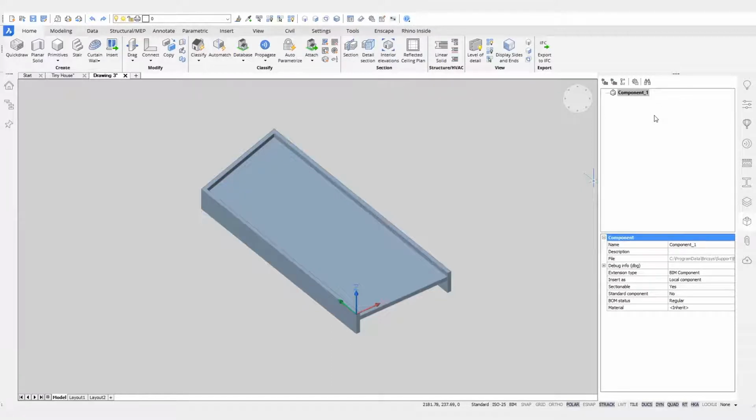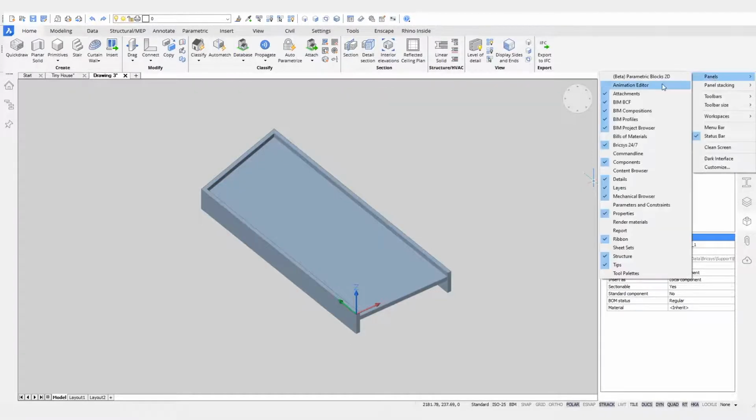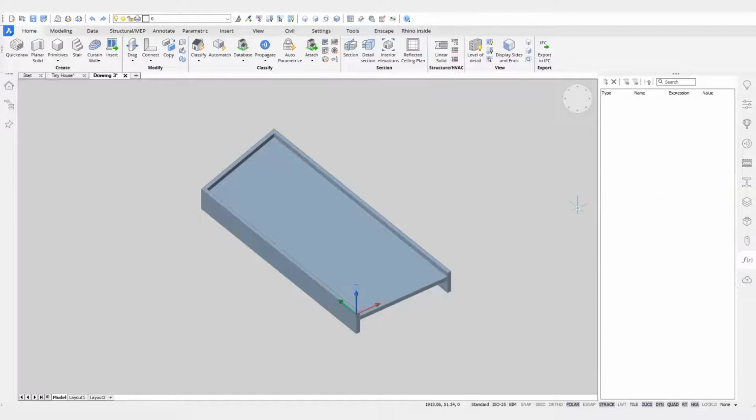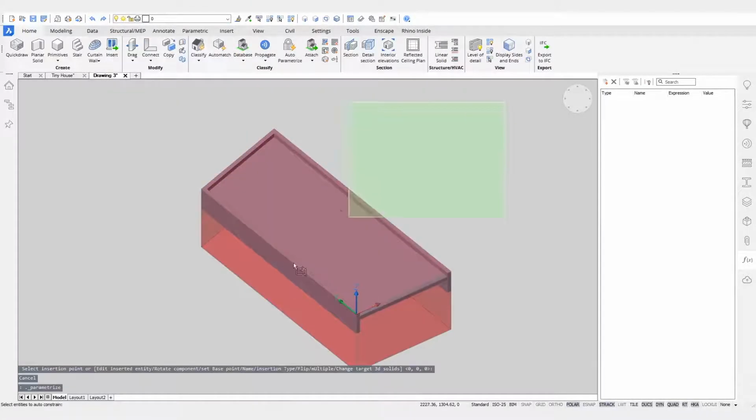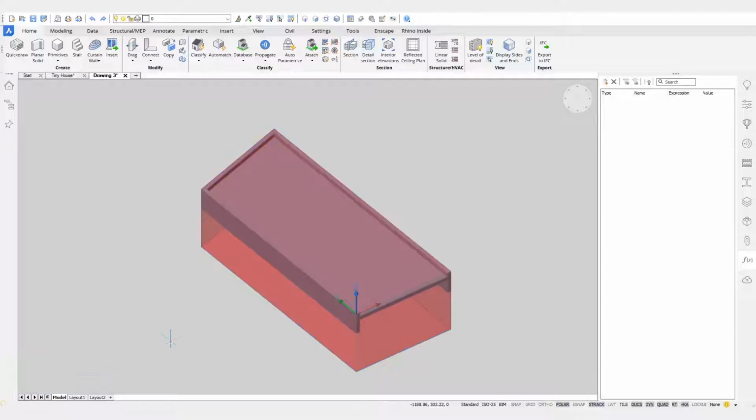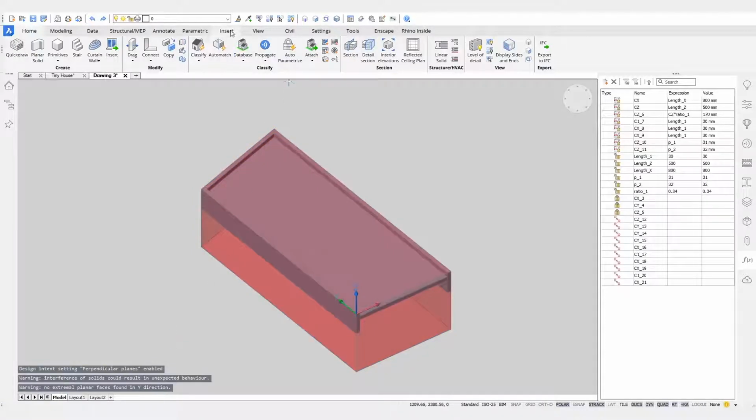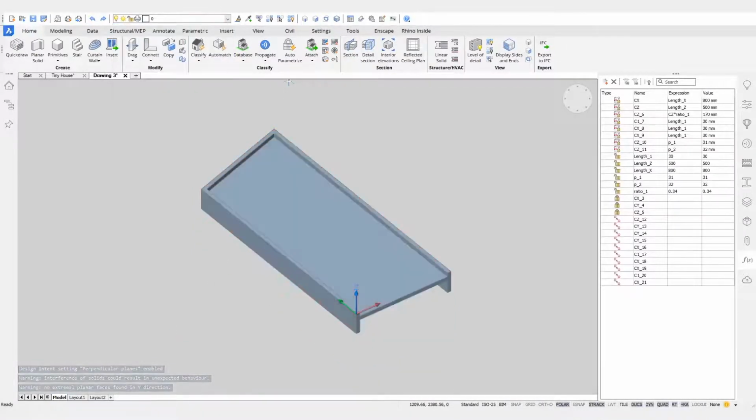There's two ways of parameterizing, or constraining. One way is to do it manually. I don't want to do this manually for the entire door. That's why I'm going to use a tool called Parametrize, which will do all of the constraining for me without over or under constraining the model. And now we see here an entire list of parameters appear. This was one of our V19 tools, but we've improved it for V20 as well.